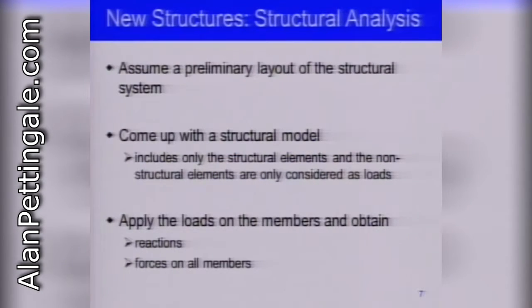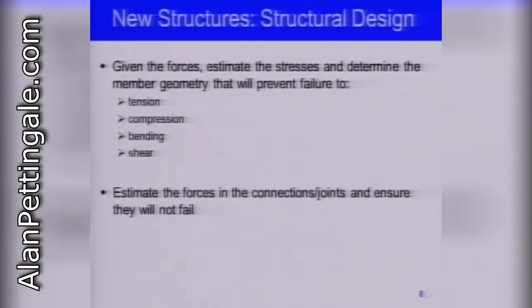And then we apply these loads, and the goal here is to obtain the reactions, make sure that we can take the loads in the foundation, and also find all the forces in the members, whether these are beams, walls, columns, braces. And then given these loads, you have to check for every single structural element that it can survive the stresses in terms of tension, compression, shear, and bending.